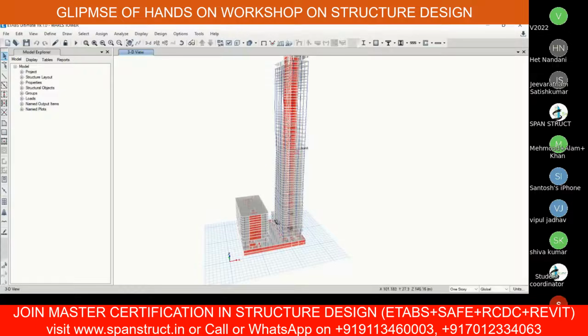Now come back here. I already explained that through Revit Structure you can import the file and do further analysis. We have DXF floor plans and grid lines. We can also import IFC files, which is one type of file you can import into ETABS. You may find IFC files in STAAD.Pro, Tekla, Revit, and many other software can export IFC files, and you can import that IFC file in ETABS.